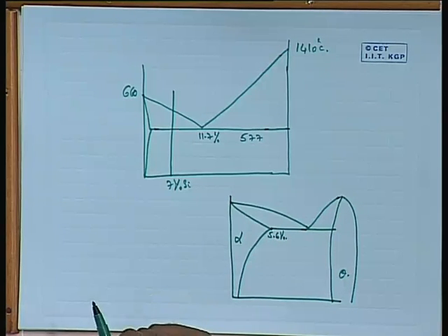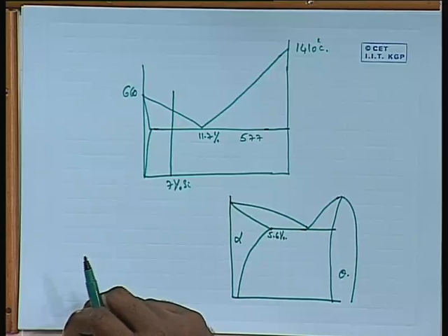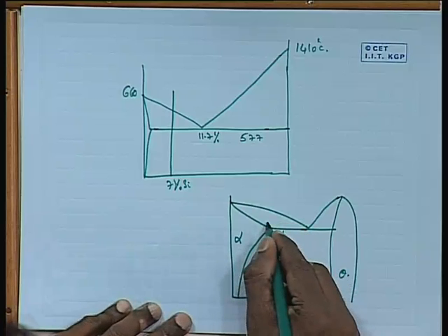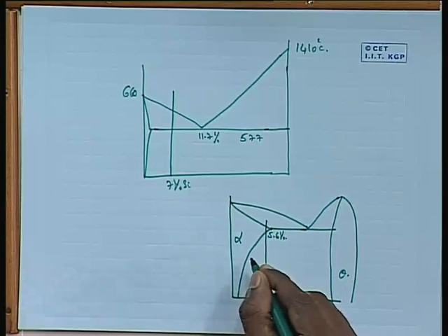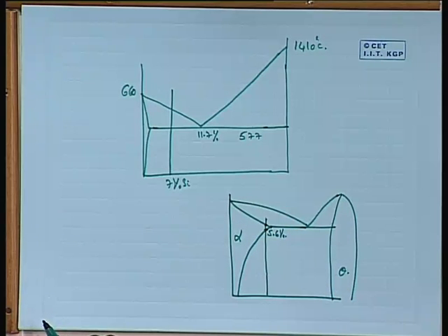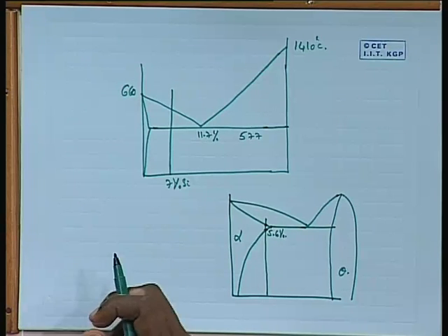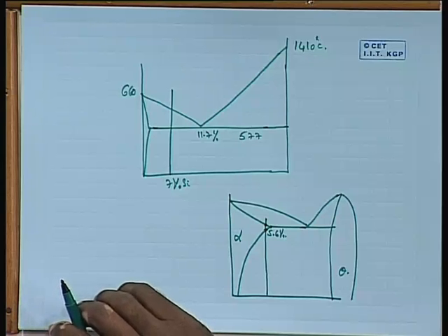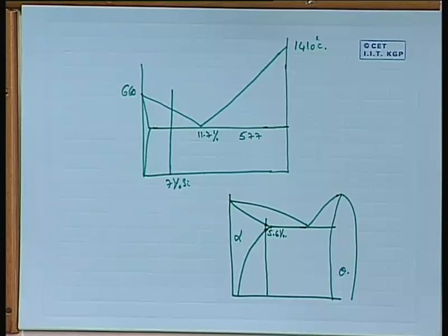So that's the maximum, but at the same time you cannot say I will make a 5.5% alloy of aluminum copper, because if I make a 5.5% alloy like this, the solvus line is very close to the solidus line. When you are doing your solutionizing treatment, there is a possibility that it can melt if your furnace is not maintained with a high degree of temperature stability. Once melting occurs, you cannot have homogenization.